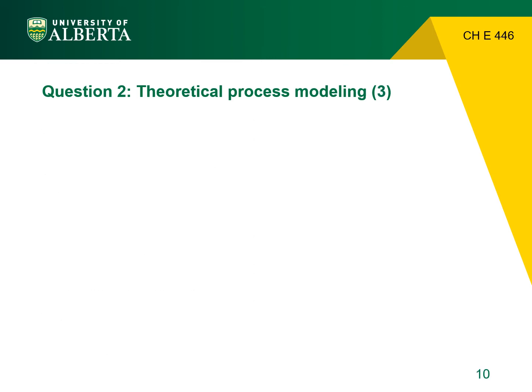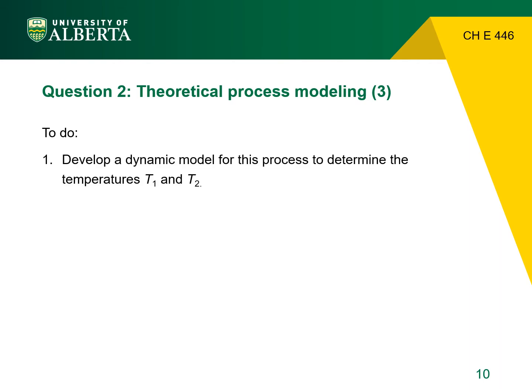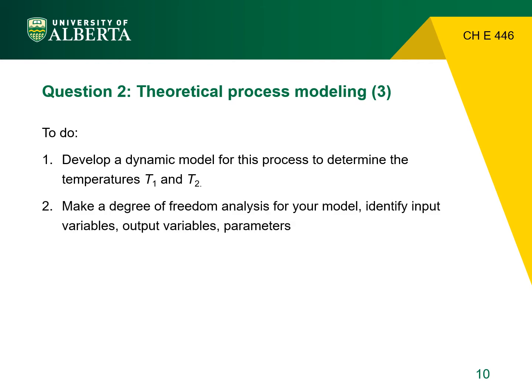In this question, we are asked to perform the following tasks. To develop a dynamic model for this process to determine the temperatures T1 and T2, as well as to perform a degree of freedom analysis for the model and to identify the parameters and variables.